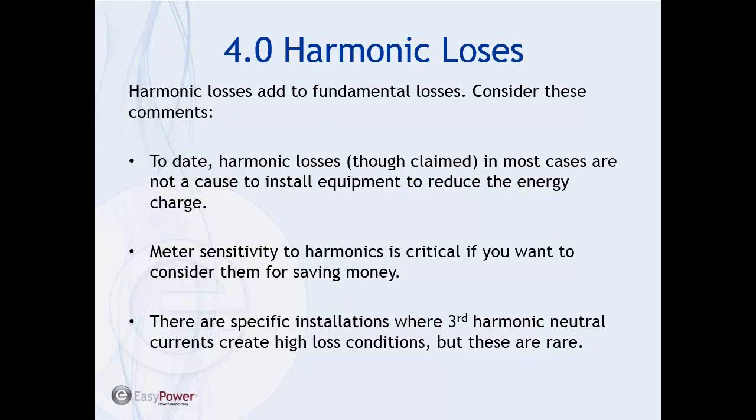Now consider these comments. To date, and I've got a lot of background on this, the harmonic losses, though claimed, in most cases are not a cause to install equipment to reduce the energy charge. I've done a ton of test cases looking at highly distorted systems, with lots of harmonic currents flowing through transformers, and in reality, the additional harmonic losses are fairly small.